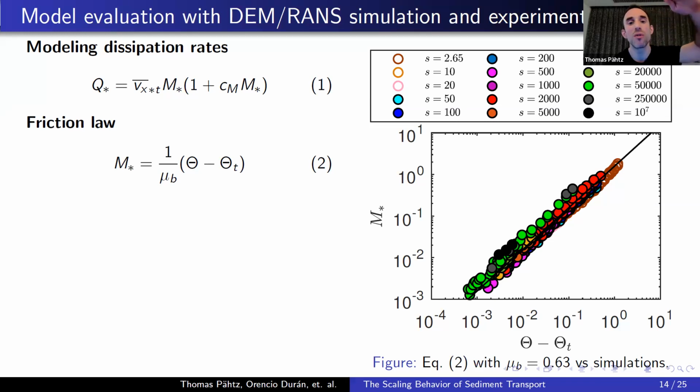So when you go from above the sediment transport layer to the bed surface, there will be particles coming that will subtract momentum from the flow, and the flow shear stress will become smaller and smaller. And if we say it goes to this threshold, it will be almost exactly equal to the threshold, so that the system is barely able to continue to move. And what we find is, roughly at least, that all these conditions can be described by a roughly constant value of the friction coefficient.